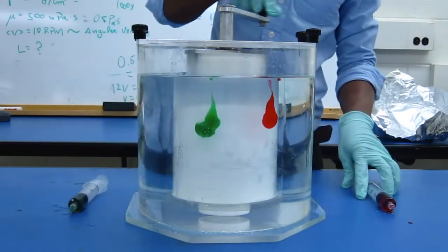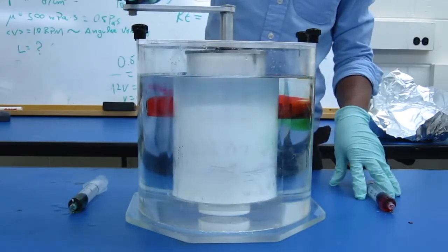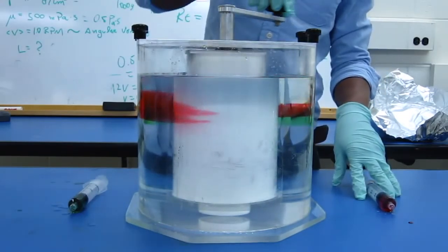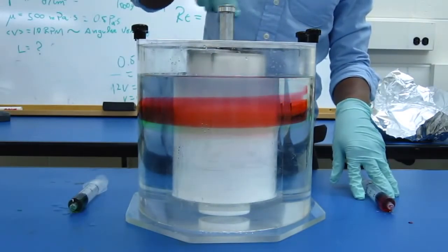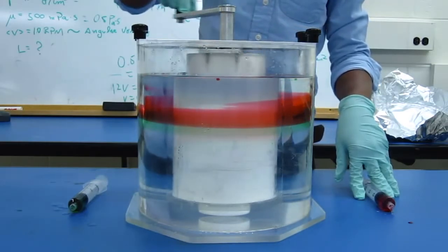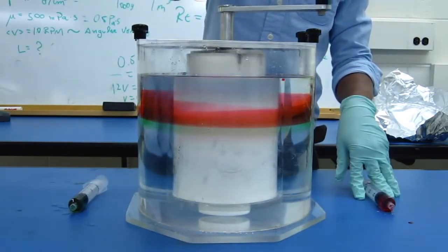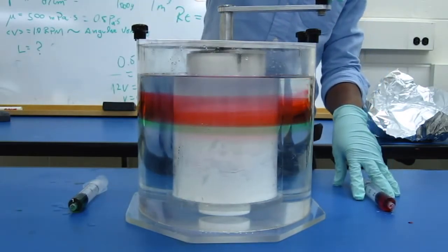What happens is you can induce the flow in one direction just by applying a force, and then if you apply the opposite force, you can make the flow move backwards in time. This video shows exactly that process. The flow causes the dye to diffuse as the stress is applied to the fluid, but if you apply an exact opposite stress for the same amount of time, you return to the exact same position.